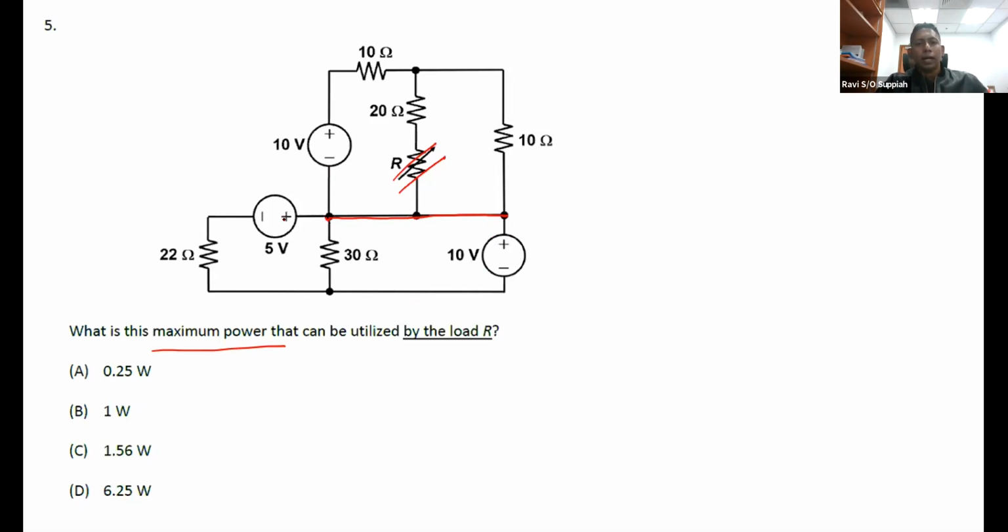Okay, again, the way you can sort of see this is, if I have the positive of the one source connected to the negative of another source directly without any component in between, then that acts like a common ground that I can separate out 2 circuits. All right, so effectively you can imagine that the only circuit you need to focus on is actually this part over here.